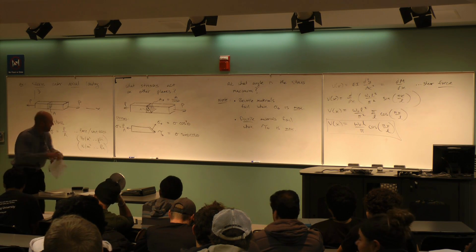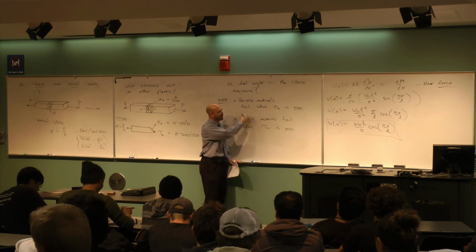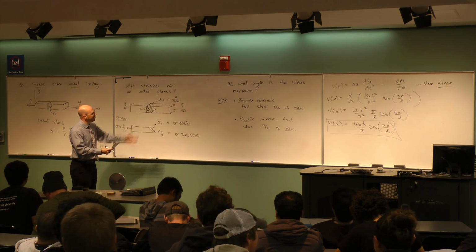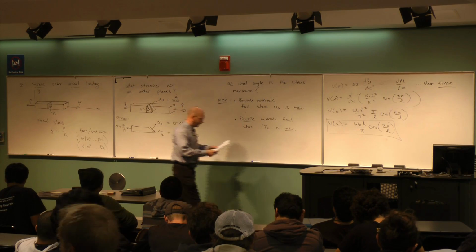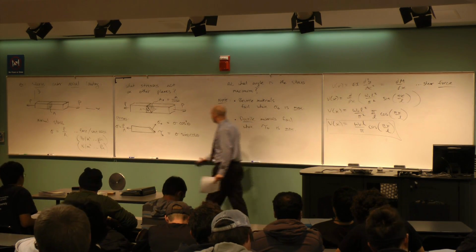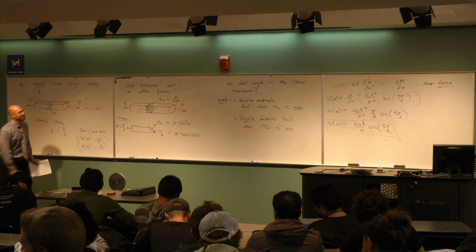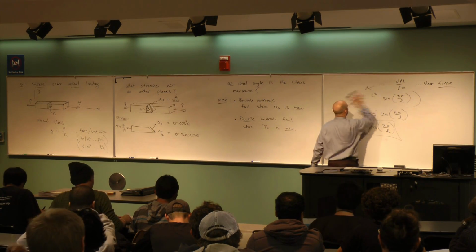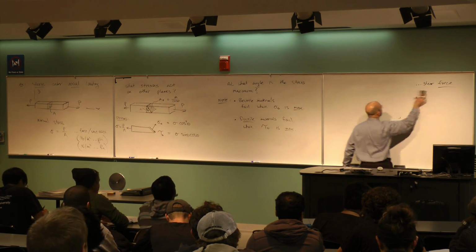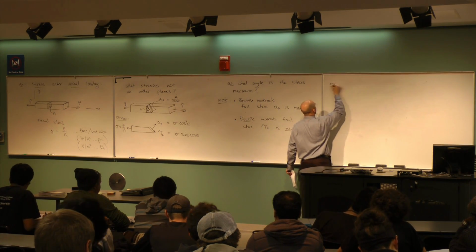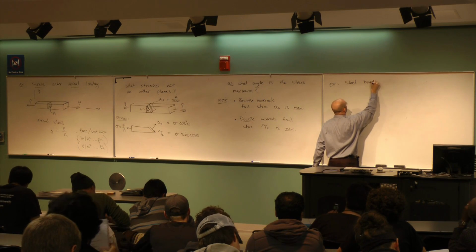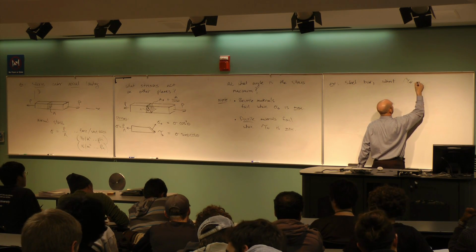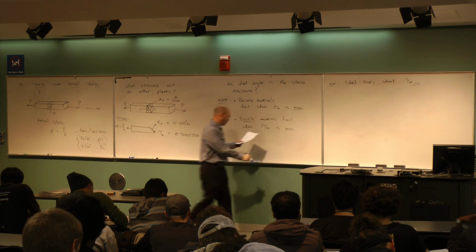All right, so far none of this is calculus. All right, so let's do some calculus. So, you know, what does this mean? I might want to think about where would be the maximum load? And so I've got some stuff in here for each of these stresses. Let's take a look at tau theta. Let's suppose this bar is made out of steel. Okay, so if it's steel, then I care about where tau is max. So for example, steel bar, what I want is tau theta max. Okay, where is the maximum value of tau theta?